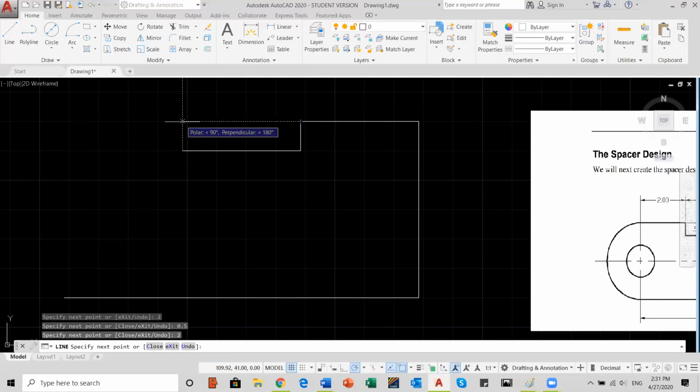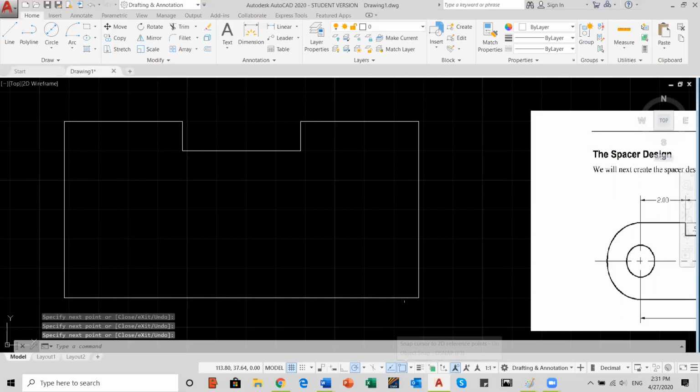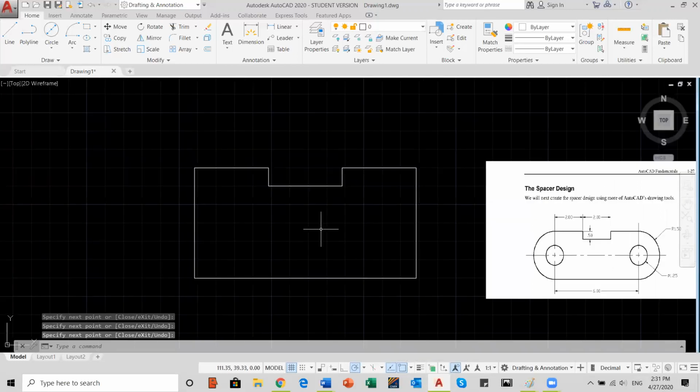Look how I track it without clicking. I just go to this point without clicking and get the lines. Okay, so I can just track the line this way and hit the point when they intersect. Then I can track it as well. I can track it if I don't need to put 2, or just type 2 and then enter, or just find the end point. It is very important to get the object snap activated. Now we finish this part.